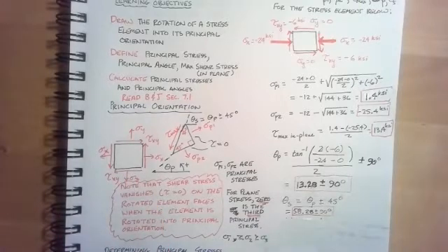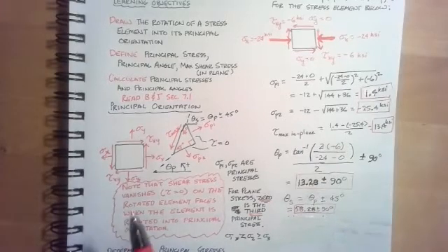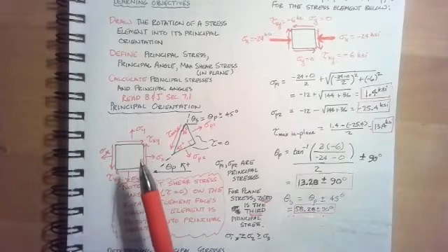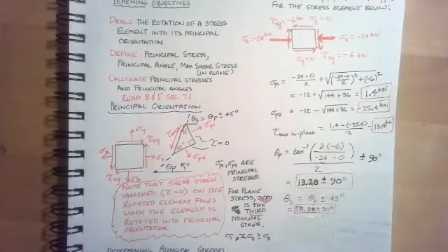However, it's usually not enough to know whether material yields to just have stress results like we had in lesson 16. We usually need to understand a little bit more about the state of stress at a particular point. In particular, what we want to obtain from stress analysis is usually the principal stresses.